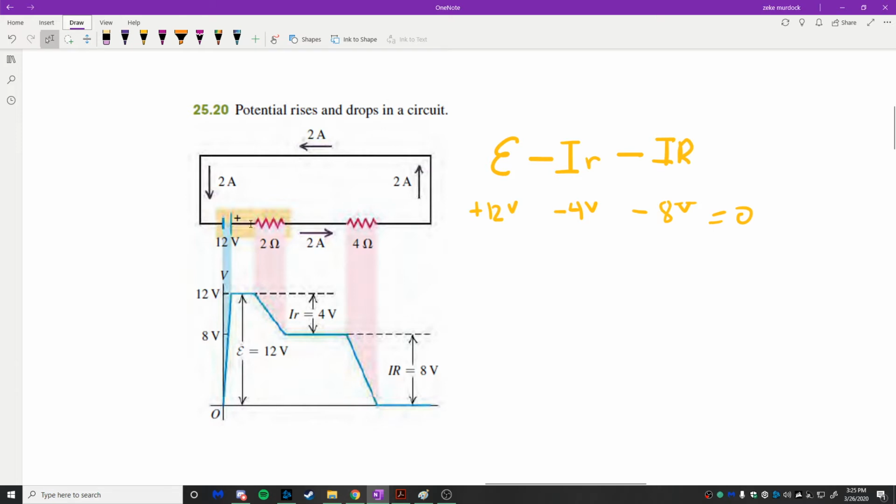But basically, every time you go through a resistor, you get a drop in voltage, and you get another drop in voltage. Then it continues back around, and you get a gain, and then a drop; you come back around, you get a gain and a drop. So every time there's a resistor or any other type of element within the circuit, because this doesn't just happen with resistors, there are other things we're going to input in here later called inductors, and even capacitors. We can talk about voltage drops on those as well. But each element of the circuit is going to effectively use up some of the energy of your battery, and we call that a voltage drop. So this phrase you're going to hear me say over and over again is that things like this represent a voltage drop. Does that phrasing make sense to you guys?